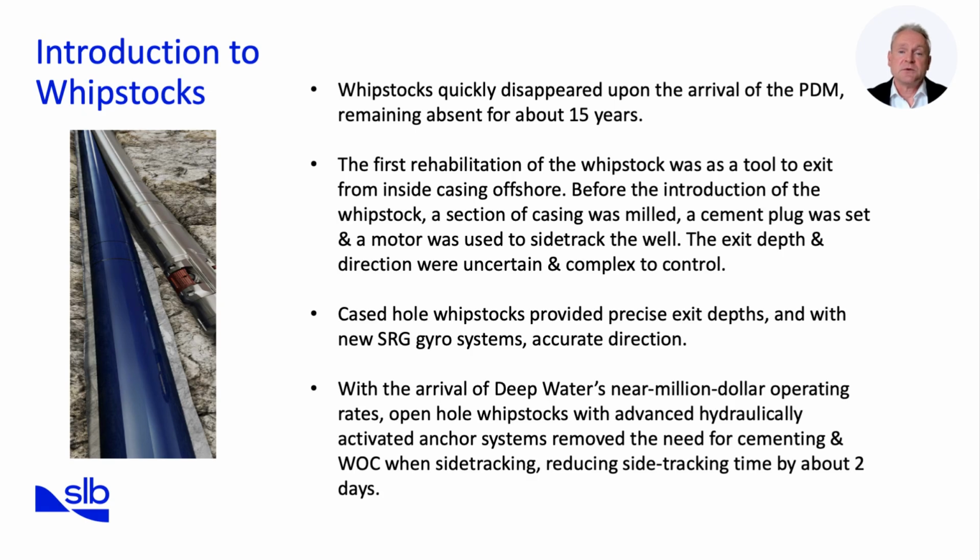As mentioned on the previous slide, open-hole whipstocks fell out of favour with the arrival of steerable motors. They experienced a renaissance in cased-hole applications. Offshore, where operators needed to sidetrack from inside casing, whipstocks offered a precise and efficient method. Previously, operators milled a section of casing, set a cement plug, and then attempted to sidetrack with a motor, a process full of uncertainty in both exit depth and azimuth.